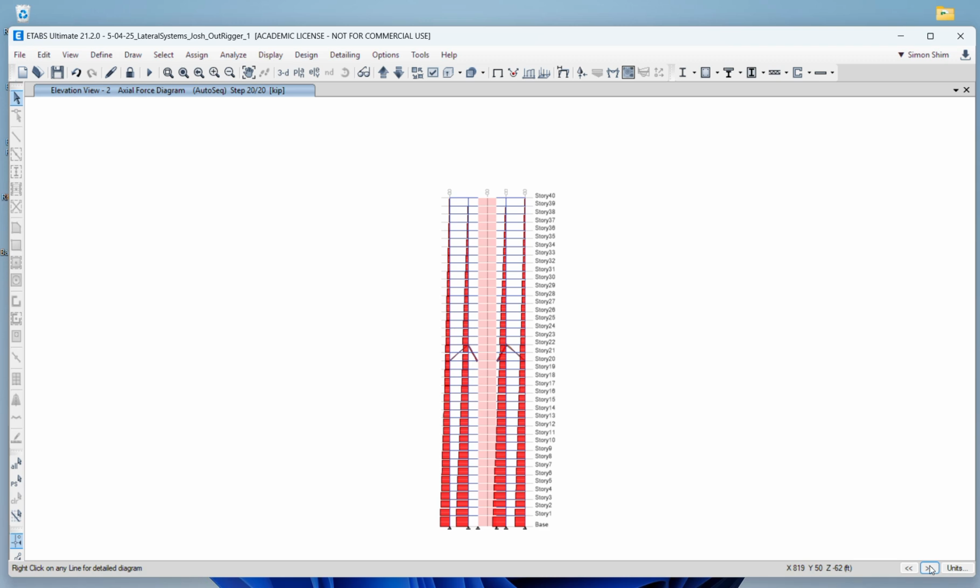So that means we are constructing the entire building without the final connection of these diagonal members. Once we build the entire building up to the top out, then we come back and permanently make this diagonal connection, so the actual forces in the diagonal member will not be generated until the building is topped out and the final connection is completed, right?